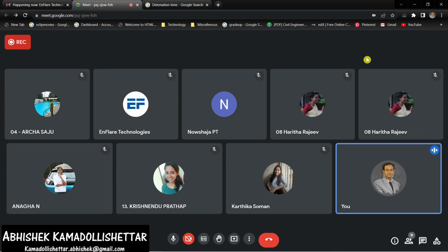So reinforcement should be in contact first, and that should be targeted to the concrete. These are basic things that some people have not implemented. If you do that, you will get the results. And one more thing: in the case of Harita, I felt she was applying the load at the wrong end, so the software is not able to give you the result. So that is one change you have to make, and you have not defined any connections there.